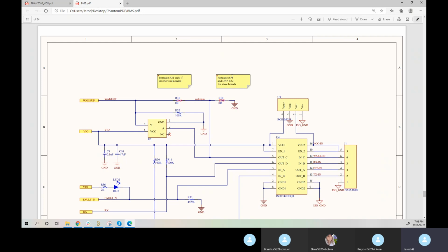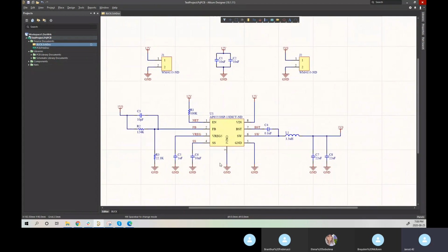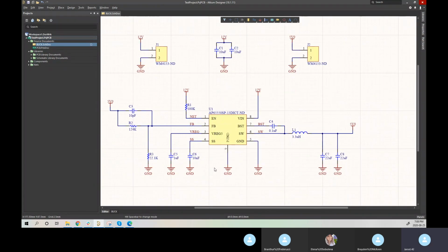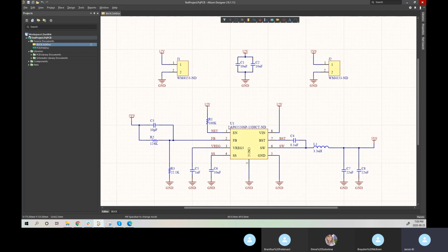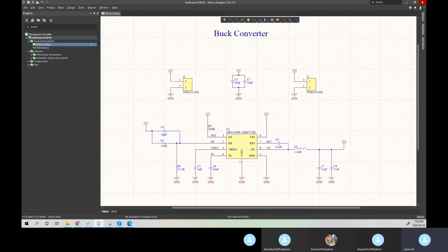When to populate or not populate is helpful. In our case, we could say, place decoupling caps as close as possible to the IC, but I wouldn't worry about it in this simple of a schematic.